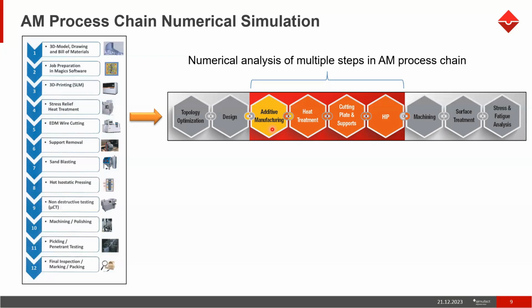I wanted to understand whether after treatment, that's where you are going to compress it, right? Correct, it is possible. Then heat treatment is also there. Some amount of distortion, some amount of sizing is also going to happen. So at that time, we can take the end result and compare with the initial CAD. Then we do something called compensation. We go back to our CAD, do some compensation, and then manufacture so that at the end of manufacturing, with all these kinds of effects, you will get the correct manufactured part within the tolerance. I'll show you that in the upcoming slides.